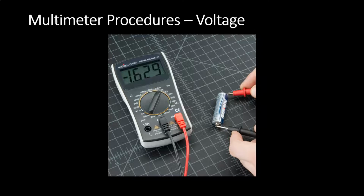In this case, they're connected to a battery, and the left side of the battery in this picture, which is at the bottom, is actually the positive terminal, and they have that hooked up to the black lead, and then the negative terminal is hooked up to the red lead. And red is typically your positive lead. So you're seeing a negative reading on the meter because it's technically connected backwards. But if you look at it, the leads are connected across the component that you're measuring the voltage of.